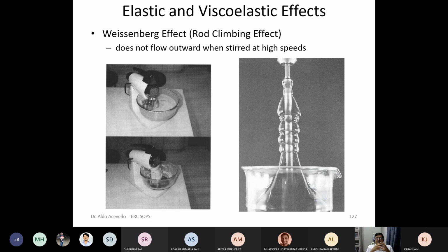So this is a very famous Weissenberg effect experiment. In general, if you take a glass of water and rotate the water with a spoon, if it is a Newtonian fluid, what will happen? You will develop a swirl which is going towards the bottom, right? So it will just go towards the flow. The way if you are rotating like this, like if you go to Brahmaputra river and see the swirl, it will create a kind of conical funnel type situation.